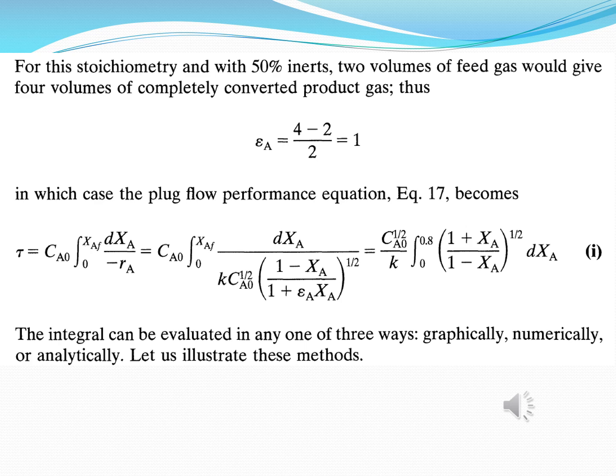So we have one part of reactant A and one part of inert in the inlet. So 1 plus 1 gives you 2, and now the outlet was 3R. Inert will also come out, so 3 plus 1 becomes 4. So we have to also incorporate the inert substance entering in the overall calculation of the volume expansion factor.